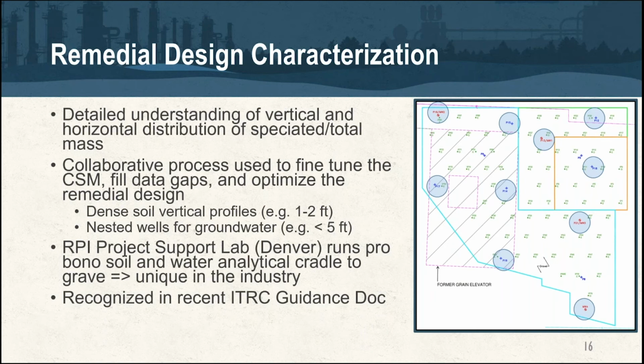So on the soil side, we're usually collecting samples every 1 to 2 feet vertically. On the groundwater side, if we've got long groundwater screens, maybe we're doing nested wells or maybe some sort of groundwater profiling. And we can do this within RPI Group because the RPI Project Support Lab that I plugged early on runs all these analyses pro bono, which is unique in our industry.